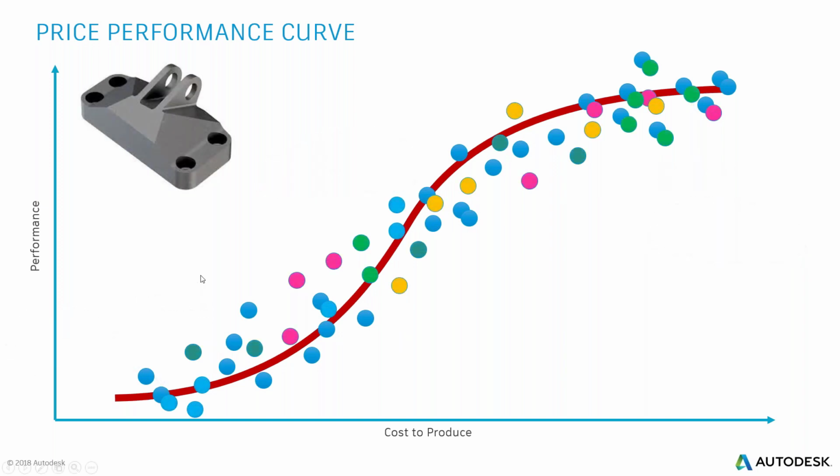So let's go into a part example here. This is the GE Aerospace bracket. You may have seen this from some other discussions. This is something that GE put forth a few years ago. They asked the user community to come up with a new design for this. They basically said, hey, here's our existing part. These are what the constraints are, and it was constrained in the 4 holes. And then in the 2 lugs here, they said these are what our loads are. We have this vertical load, we have this horizontal load, we have these particular moments. Let's see what you can come up with.